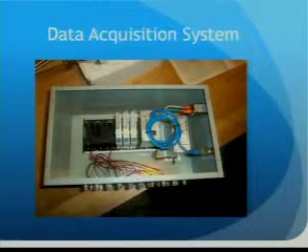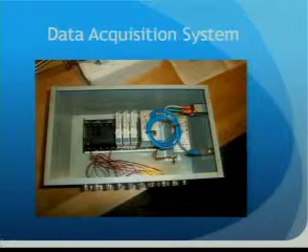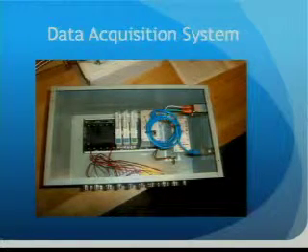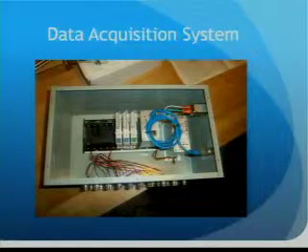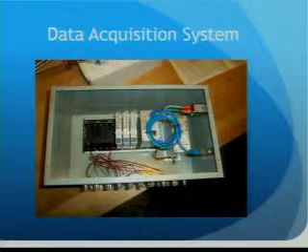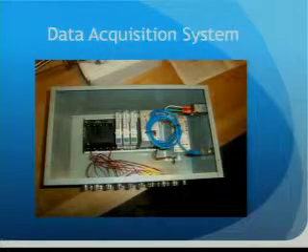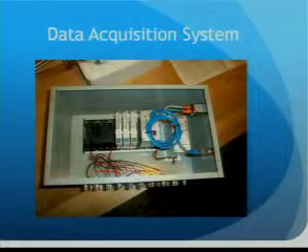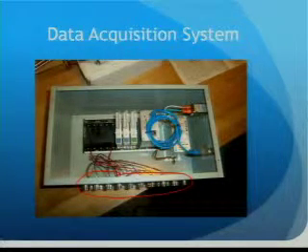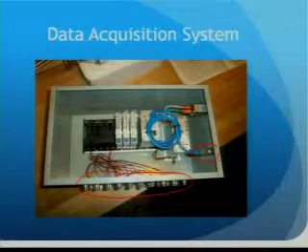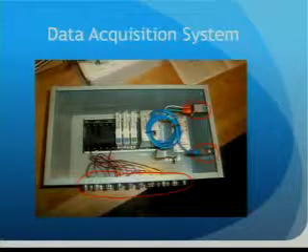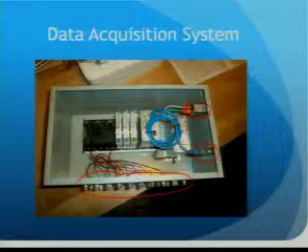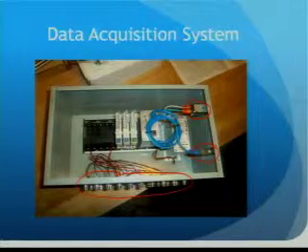My second project dealt with the data acquisition system. Electrical information is very important when taking diagnostic measurements. Therefore, a data acquisition system was already in place. I improved the user-friendliness of the data acquisition system by machining the enclosure shown in this picture. As you can see, this front panel consists of 20 BNC connectors to connect to the modules. The side panel has an Ethernet connection here to connect to the brain, to the computer for LabVIEW interaction, and an AC power connection here for the power supply. Also, the enclosure has an easily removable top for easy access to the modules to modify or change the modules.